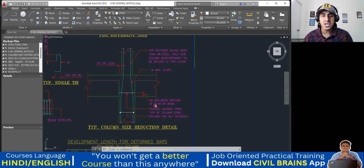What is it trying to tell us in this particular portion? 50 mm max above the bottom of the slab or beam. That means this will be your slab or beam bottom. From there, up to only 50 mm, this portion should come. This much portion you're bending. So this should be 50 mm maximum above the bottom of the slab or the beam. You cannot go up to here too much and then take it like this. That is what it is telling us.